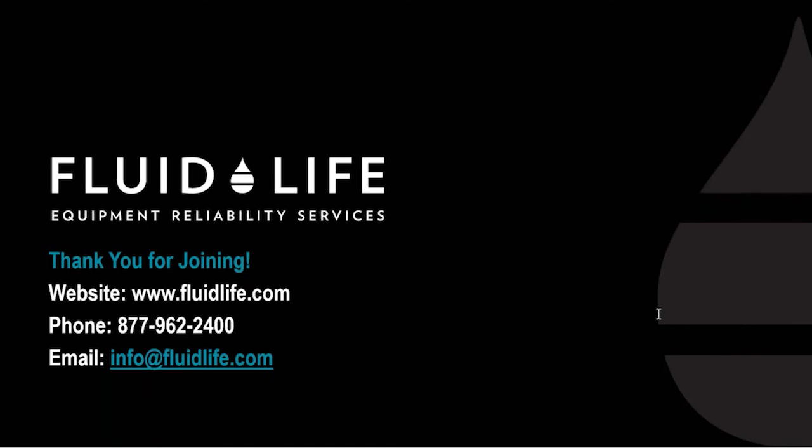Silicon, you're definitely going to see that, because that's alloyed steel as far as a wear metal is concerned. And then same thing, silicon and aluminum is a lot of the time attributed to dirt ingression, and just natural contamination is going to happen. So that's how we can offer our value in terms of interpretation: we know where some of this stuff comes from in a general sense, and I'm applying it to the application that exists.